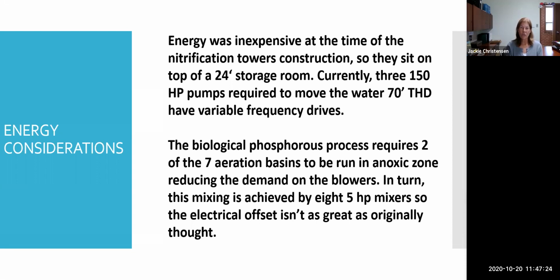How much mixing is required is a little plant specific, depends upon where you're running your mixed liquors. Out of the 8 mixers, we know we can survive without 1. If we lose 2, we're going to have a problem with our phosphorus.